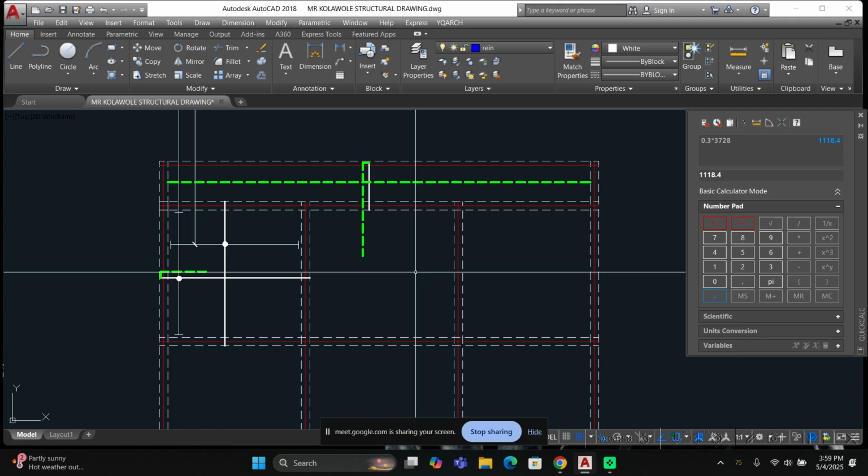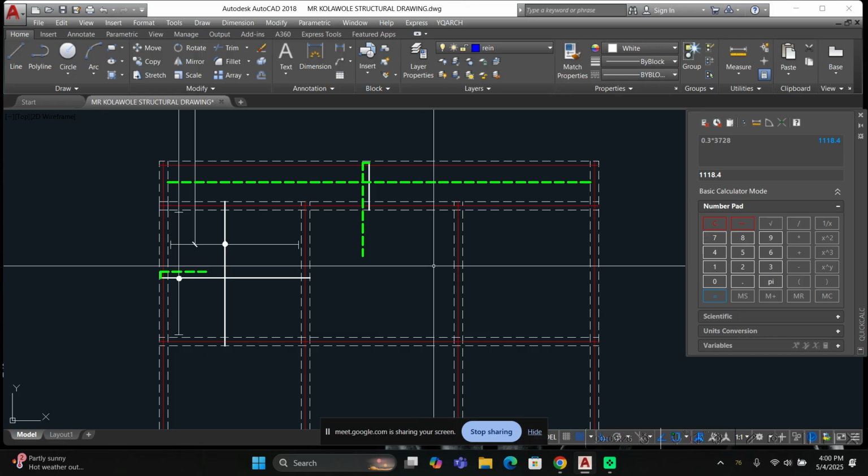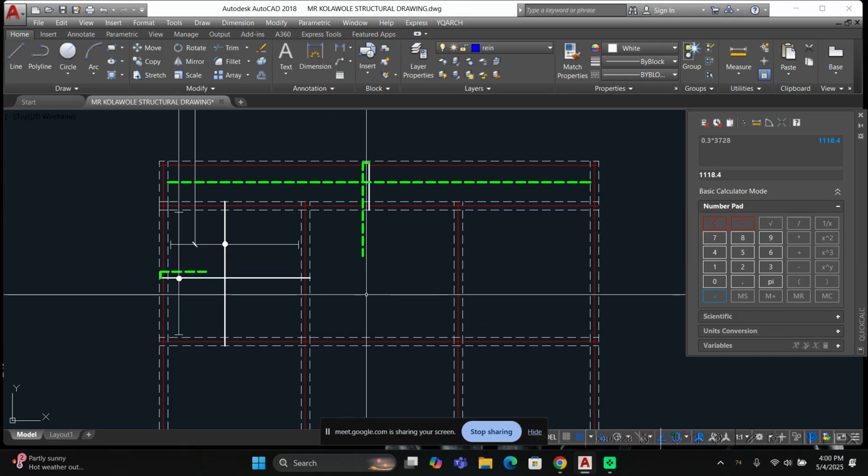Because of the deflection and all of that, it has a point load. There might be a wall load there and all of that, so you have to treat that. That's going to give you the design results so that you can know. But right here, you can write it down: for a cantilever slab, we have two reinforcements. We have the main reinforcement, which is the top bar, and the distribution bar, which is also a top bar. Do you get it now? Yes, sir. I've written it before.